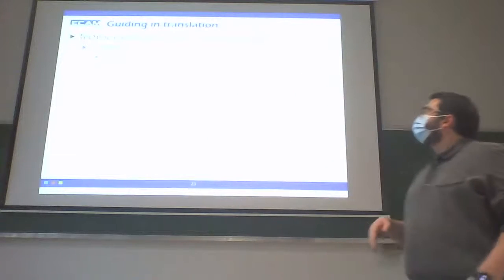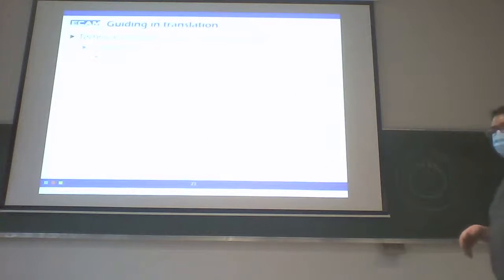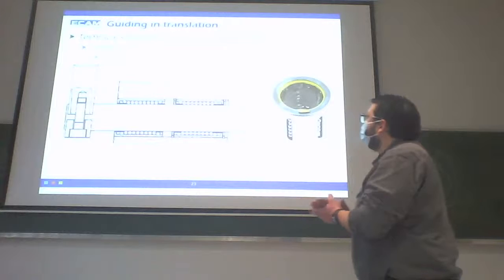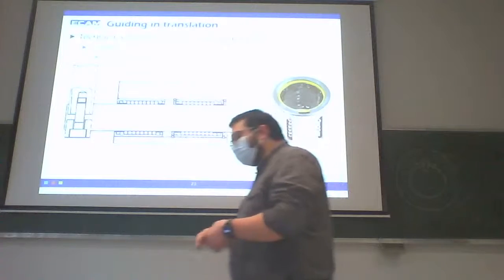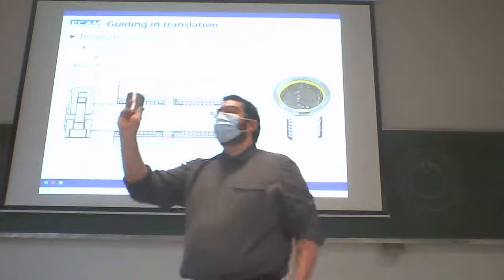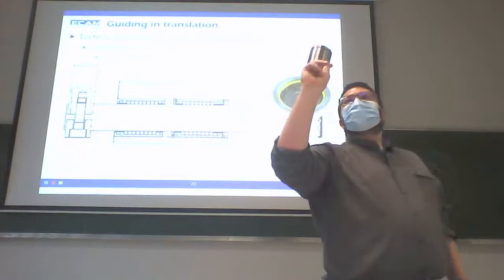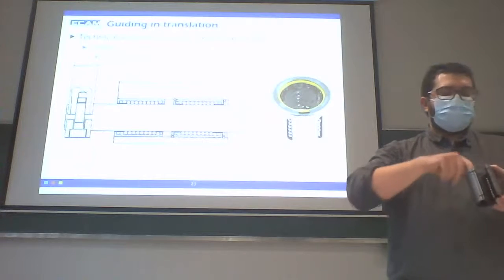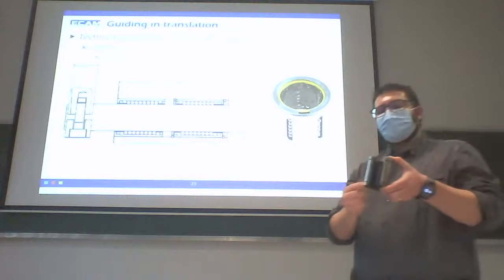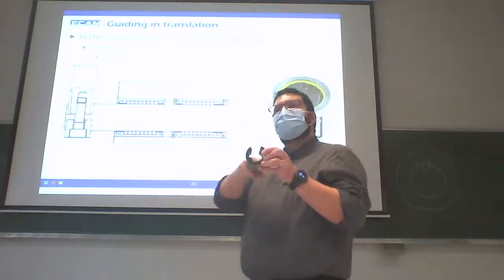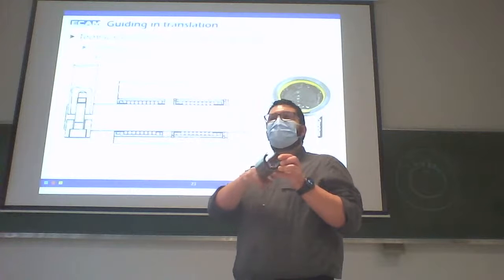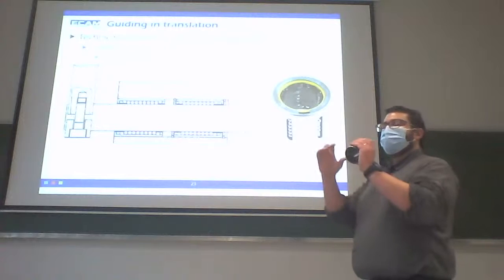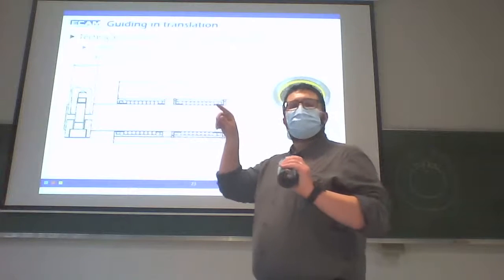So to realize a passive resistance solution for a sliding joint, we have different solutions. First one is the linear bearing. It's a part like this. Inside this part we have some small balls with a system of circulation of the balls inside of the part that will reduce the friction between the two parts. If we use this, we can add two of this solution to realize the double stem of the previous one.